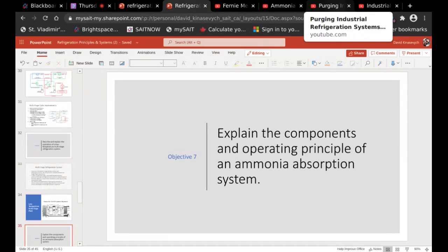That's how we know. Our high side pressure is too high, but we look at the high side temperature, and the high side temperature looks just fine. The pressure is too high, which means that our compressors are working harder and they're consuming more energy to get the refrigerant from low side pressure to high side pressure. That's one of the problems. Now, also we could have a high side pressure that exceeds the maximum design pressure and start popping safety valves. We don't like that. We can get a high side pressure that trips the machinery off before the safety valves pop, so we've got high pressure cutoffs on the system. We don't like that. We don't want our system tripping off.